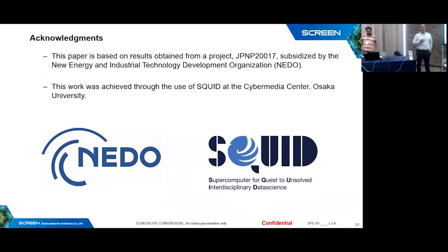So first of all, can you repeat the question? Because I have to repeat it to the audience. Okay, I guess in short, do you have a resolved turbulence spectrum in your LES? Okay, so no, and I will say why. Because for us, we work in low Reynolds number. So we didn't expect turbulence at all.